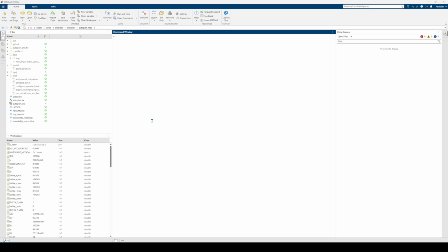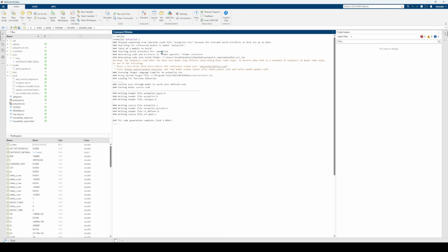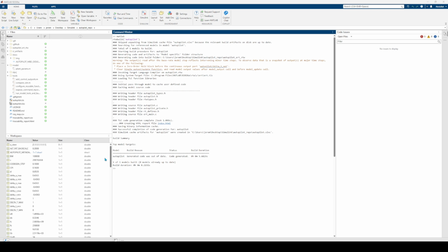Both models code gen the same way, 1 command each. And so the Embedded Coder produces Portable C from the block diagram, configured for reusable function packaging, so that each aircraft gets its own autopilot, no shared globals.